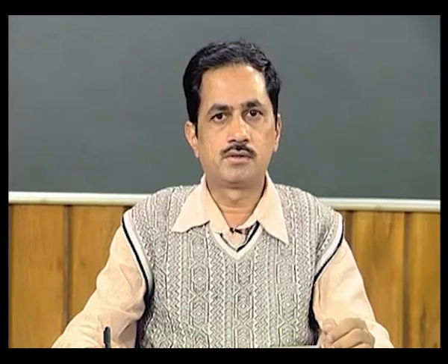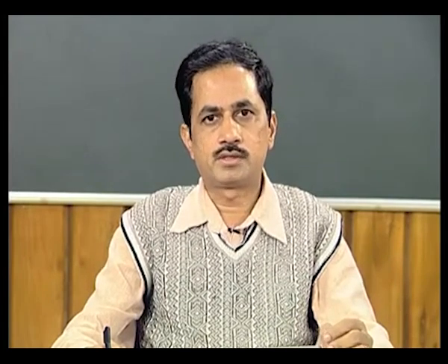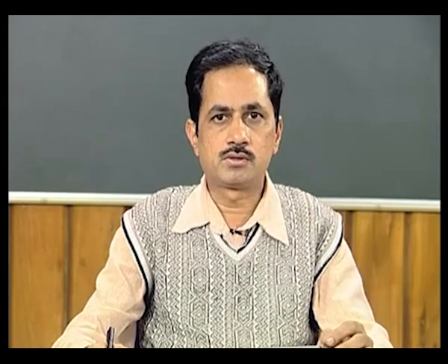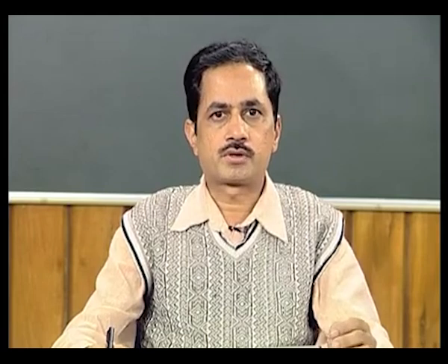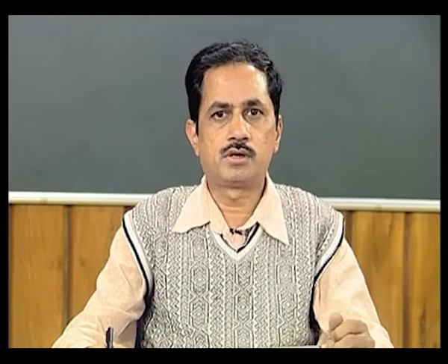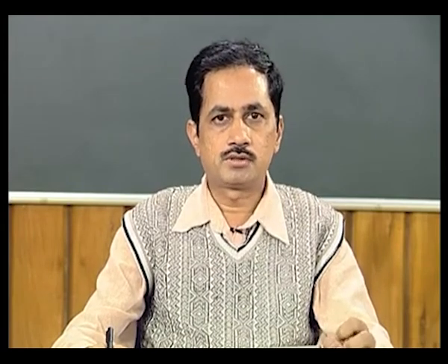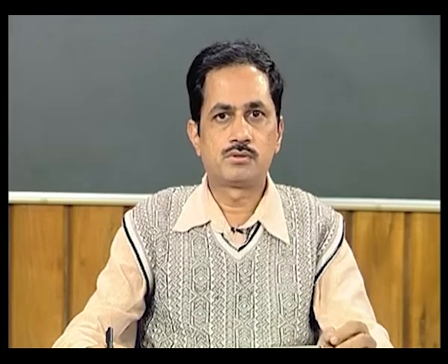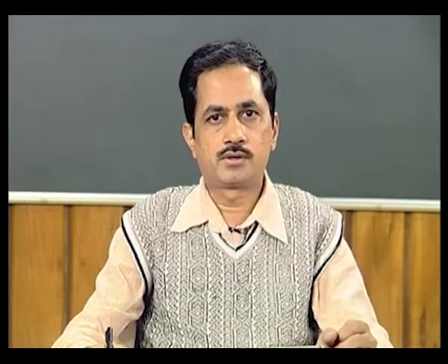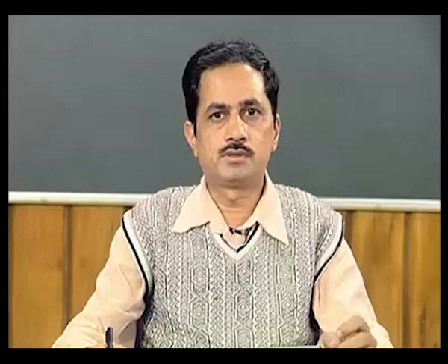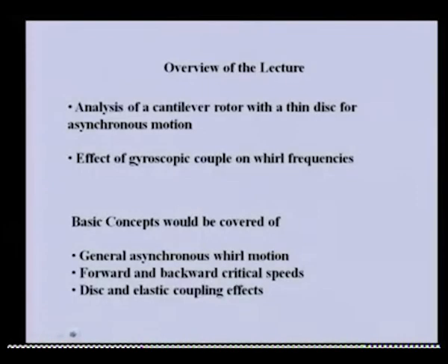We will take an example of a cantilever shaft attached with a thin disc at the free end, and we will analyze the asynchronous whirl condition, and try to find out how the whirl frequency changes with the spin speed of the shaft. Also, from the Campbell diagram we will be able to obtain the critical speed of the shaft system. So this is the overview of the present lecture, in which we will analyze a cantilever rotor with a thin disc for asynchronous motion.